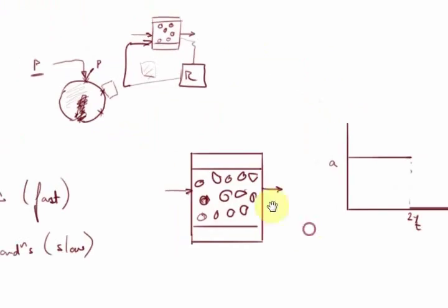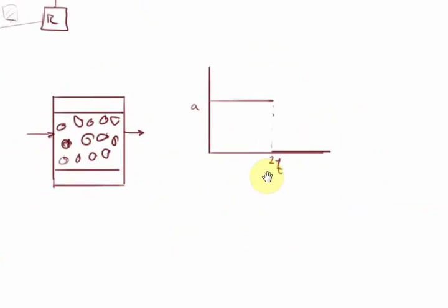So, of course, in terms of what we described here, this is going to be a continuous process. Continuously we might be blocking off pores, or continuously we might be getting coke depositing slowly. So what will actually happen is that we will lose this activity over time. What we would rather do then is to quantify this loss of activity. If we know how fast we are losing activity, and if we know that activity as a function of time, then we could look at operating this reactor such that we achieve the same reaction rate as we had initially.